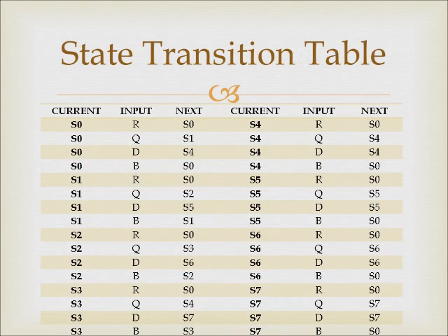Based on the specifications put forth by the team, this was the state transition table that was produced. This state transition table was used for the Karnaugh maps that would produce the logical equations our group needed to drive the J and K logic networks in the state machine.